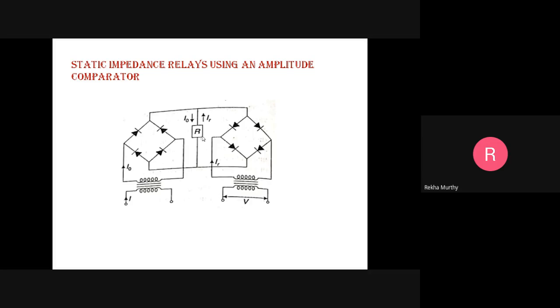Next, coming to when you're going to worry about its phase angle. So we have to think about its phase. An impedance relay characteristic can also be realized by using a phase comparator. So let me consider your RX diagram which you had drawn in the previous session for an impedance relay. The radius of the circle is considered as ZR.